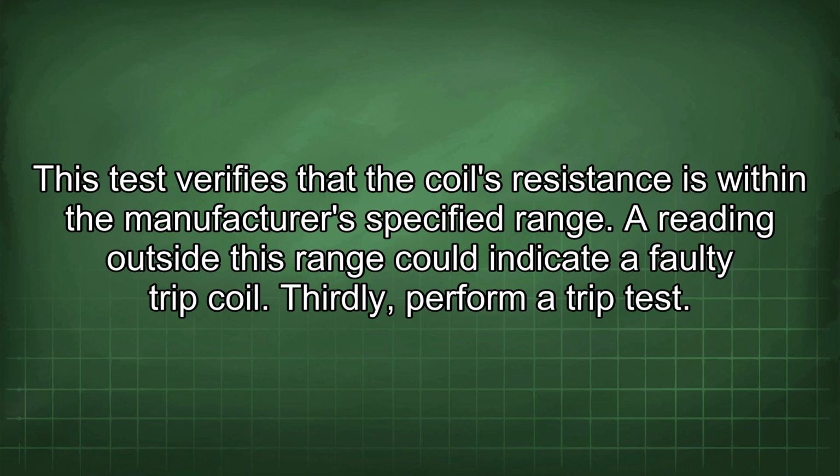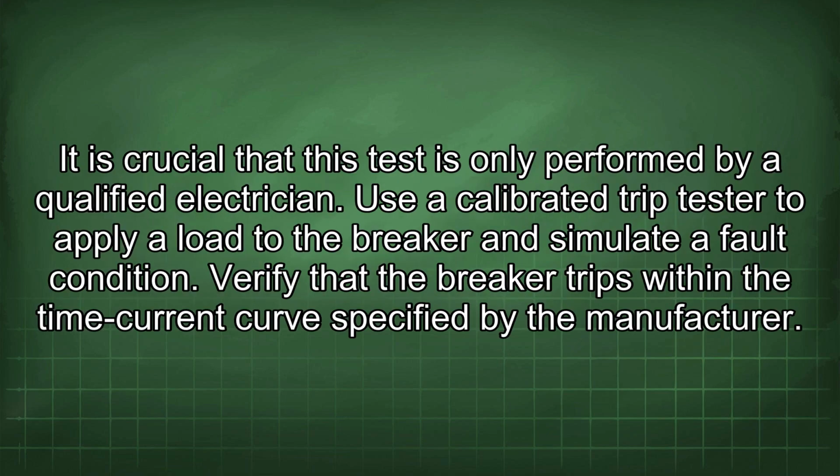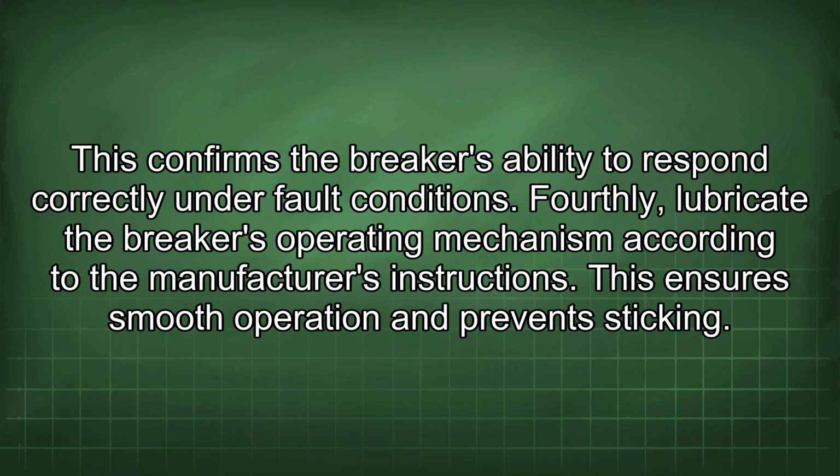Thirdly, perform a trip test. It is crucial that this test is only performed by a qualified electrician. Use a calibrated trip tester to apply a load to the breaker and simulate a fault condition. Verify that the breaker trips within the time current curve specified by the manufacturer. This confirms the breaker's ability to respond correctly under fault conditions.